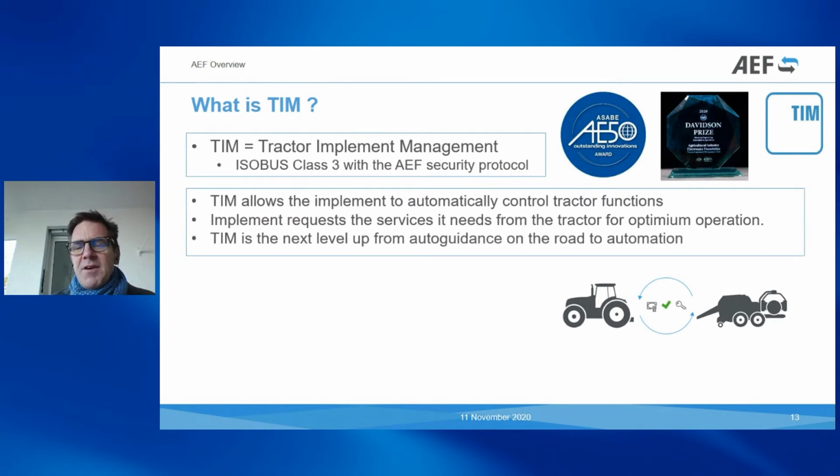And the idea is that any manufacturer who passes the AEF conformance test and can be certified for TIM gets specific security keys from the AEF, and any AEF certified TIM product can work with any other AEF certified TIM product. And why is the certification so important? Because you're actually saying that I'm allowing this implement that I've connected to the back of my tractor to control certain functions on the tractor.